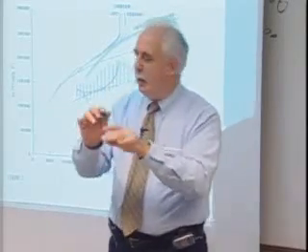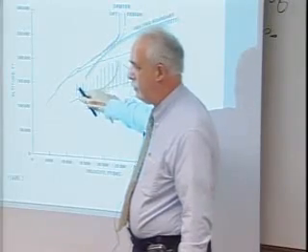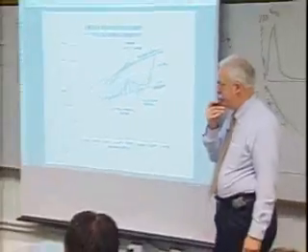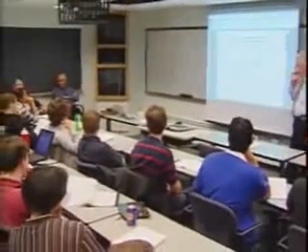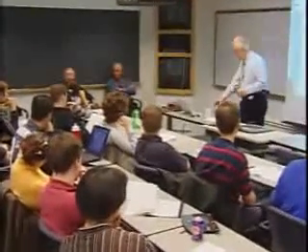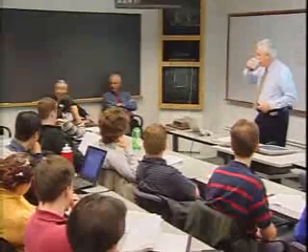Then we worry about getting down to a landing point. In terms of corridor, they term that corridor. The Apollo vehicle had about a 27-mile corridor at 400,000 feet. That said that if you were too shallow, then you would skip out. If you were too steep in that corridor, you would go in too deep and exceed the G load.